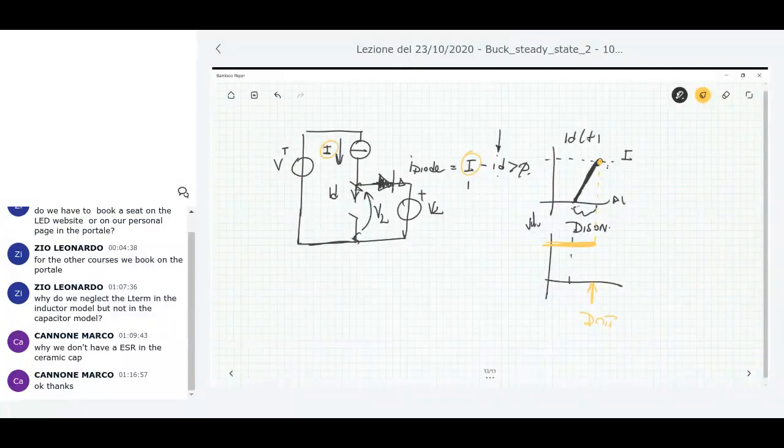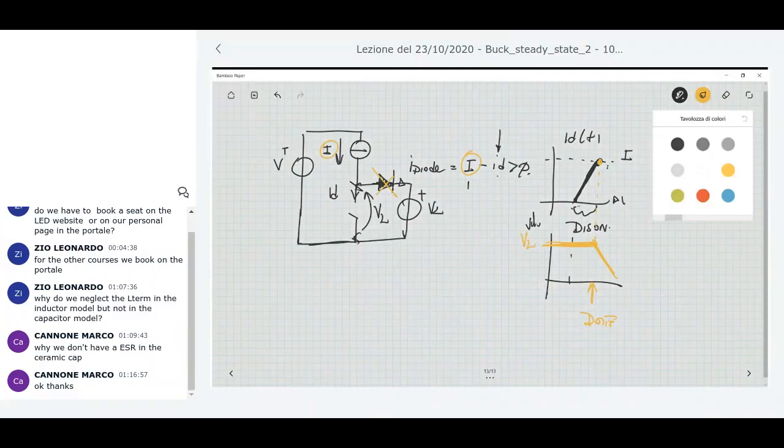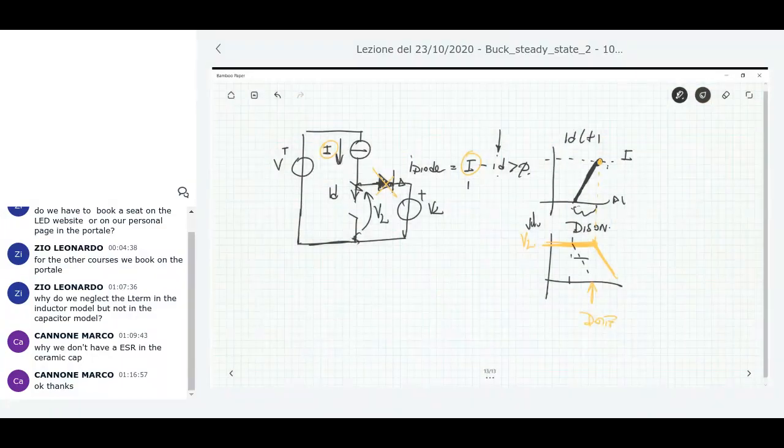And when the diode becomes off, then the voltage VDS is no more clamped to V2, it can go down. And so with respect to the situation in which the load was a resistance, now there is a shift of the voltage VDS toward the left.